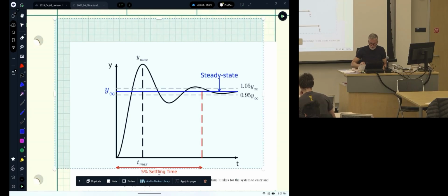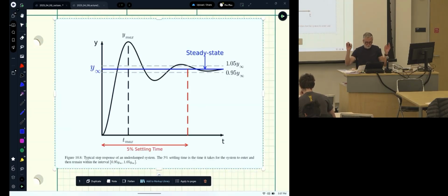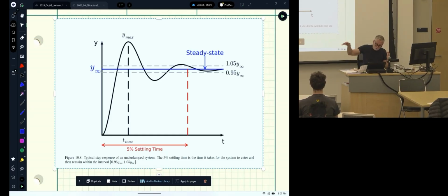Okay, so here's kind of a typical step response. It's called a step response when you put a unit step in and then you look at the output. Why do people like to use unit steps when they're tuning a control system? It's because everything is quiescent, nothing's happening, and then boom. So you're hitting the system, and anything that is slightly oscillatory, you're exciting it, okay? If you've got some things that want to oscillate, they've got the energy with that boom. That's a unit step.